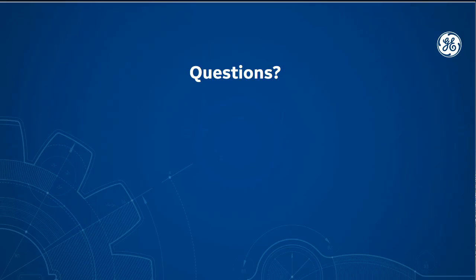Here's another question. Can this protection be implemented by negative sequence current detection or broken conductor protection? Well, before HIF that was kind of the way we did it. Negative sequence current detection is the I2, I1 method that I discussed in the presentation. It's a traditional method to detect a broken conductor. It measures the ratio of the negative sequence current I2 to the positive current I1, as I stated. It works because a broken phase conductor produces an unbalanced current in the system.